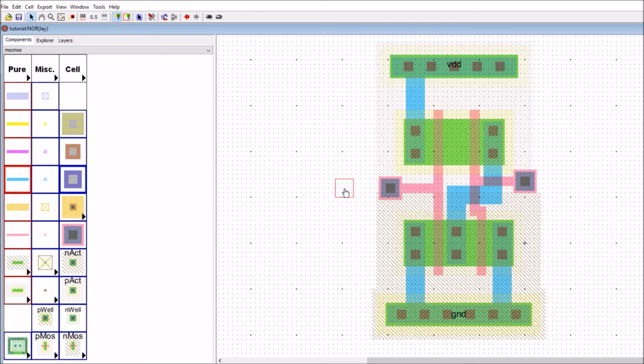So we can bring it in here, and we can left click, right click, and that gives us a metal 1 to metal 2 connection here, and we can shovel it in here. So basically both of those vias, they'll go one above the other. And again here we could grab this one, pop it over here, we can left click and right click, and we can shift this in. And again we can do the same for this one, we can bring this one in, and pop it here, and we can left click, right click, and then we can just move it into position.